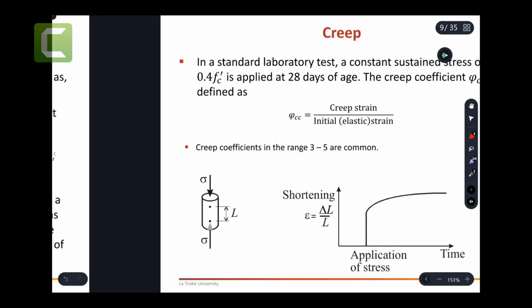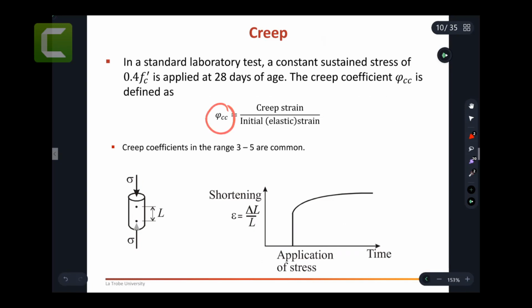So the two parameters, on the next slide here, this is from the standard. As we said, this is the creep strain. And this strain will help us to determine the level of shortening the slab will end up experiencing, and eventually deflection. So step by step, this creep strain will give us a figure about the overall shortening the slab, or column or beam, is under, and then that shortening can be re-simulating the sagging or deflection.